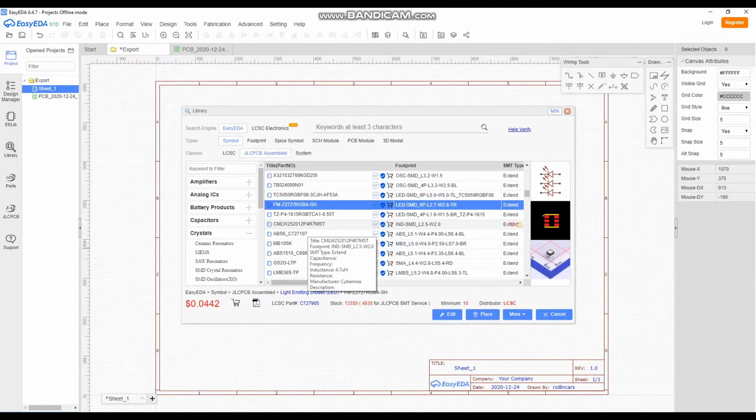And then I'll talk about how to export your Gerbers, everything, and then your pick and place files through Altium or Circuit Studio, and how to actually get that through to the JLCPCB website, and then be able to use their pick and place service without having to use the EasyEDA development tool.